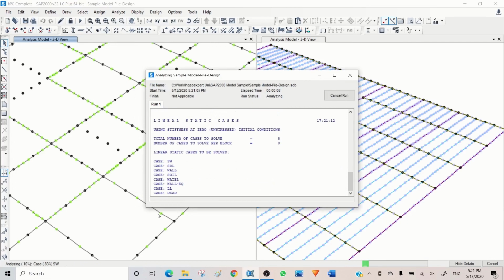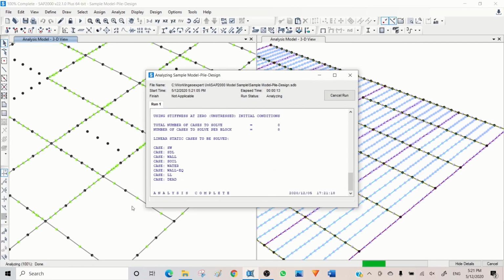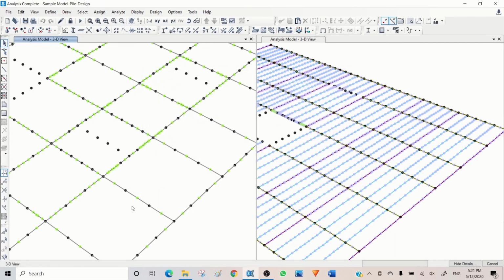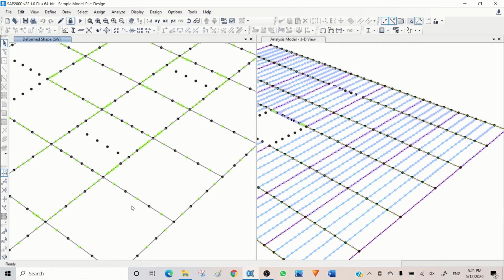Okay, so what we did, we reduced the stiffness of the slabs significantly. The consequence is having some shifts in frequencies when the modal analysis is being done. To avoid this, as you saw, I deactivated running modal analysis to save the time.